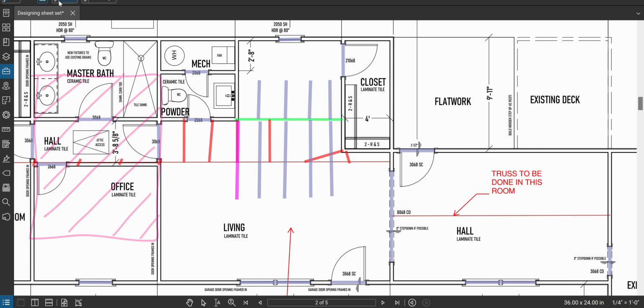So this beam is holding these ceiling joists, but it's only holding halfway to the other side of the support. So the ceiling joist that exists right here, half of the weight goes that way to the wall, the other half goes this way to the beam. I'm designing the beam, I'm not designing the wall. So I want to know how much weight the beam is responsible for holding. The answer is the halfway point to the other support of the ceiling joists. So let me get rid of these guys here.